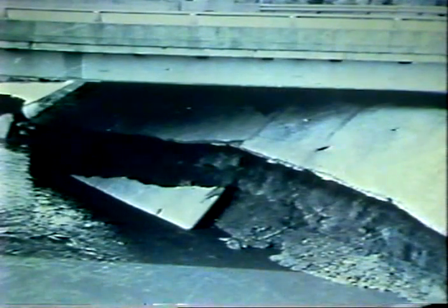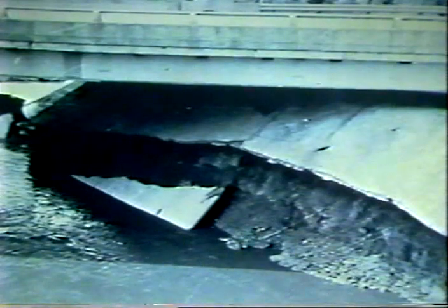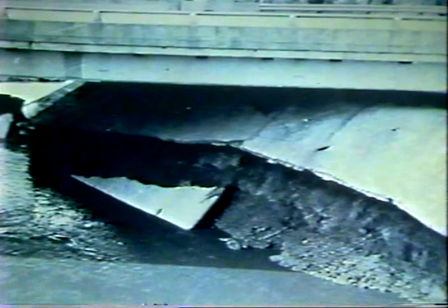Although concrete slope pavement is in general use at bridges in several states, it requires substantial toe and end protection from undermining. Failure, when it occurs, tends to be progressive, as at this bridge. The damaged concrete pavement was replaced with concrete-filled fabric mat, which has not been tested by a flood at this site, but has proved satisfactory at other locations. It has some construction advantages over concrete pavement and has less effect on flow conveyance than riprap.